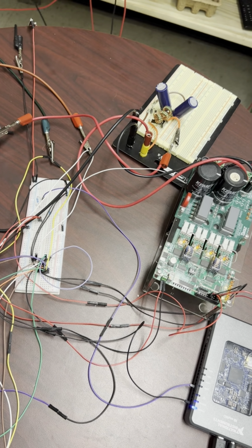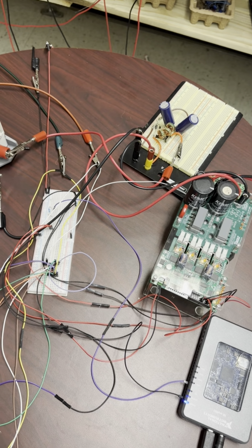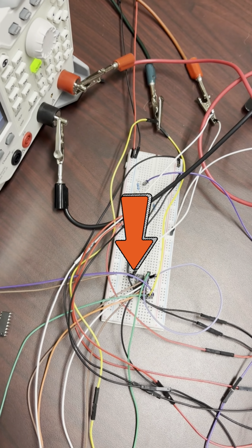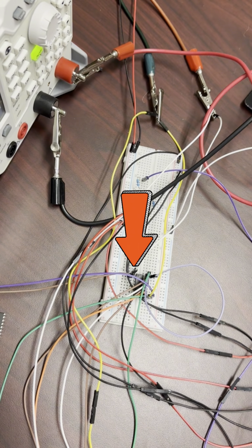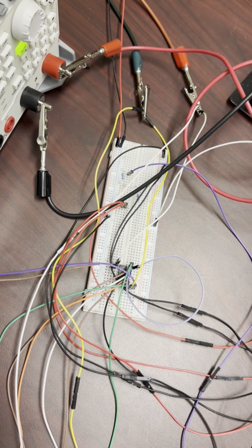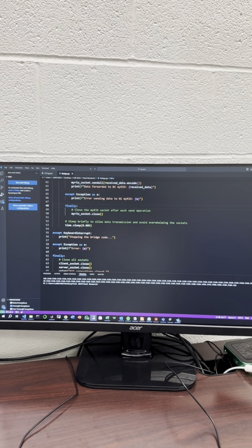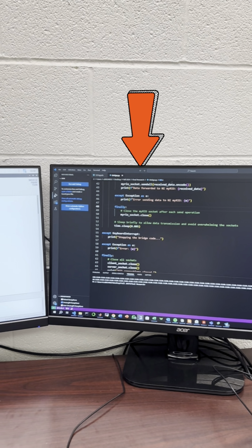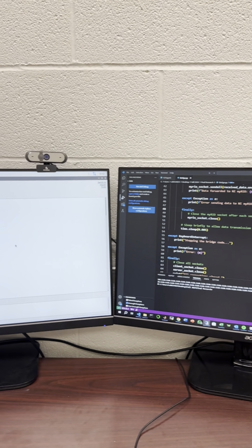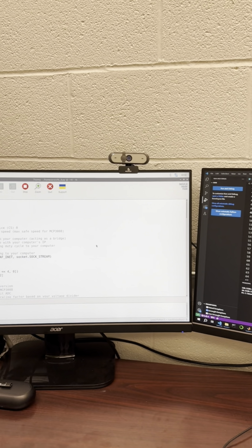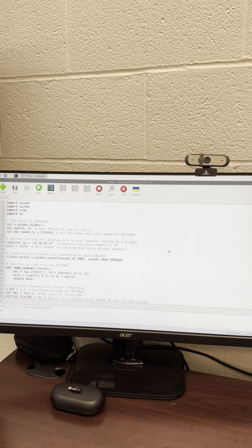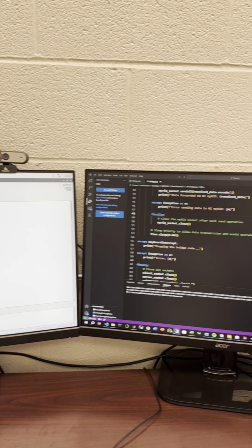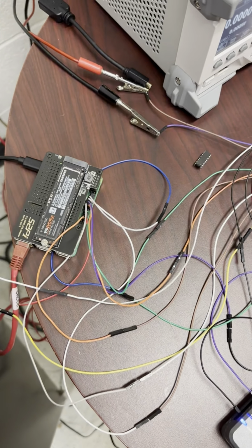Since the programmable load provides only analog data, here I use a microcontroller, which we call MCP, to convert this analog data to digital, allowing the Raspberry Pi to process it. Once the data is digital, it's sent to a server on my computer using the TCP communication protocol. All devices in this setup communicate indirectly through this server. This approach enhances the security and ensures reliable data exchange.